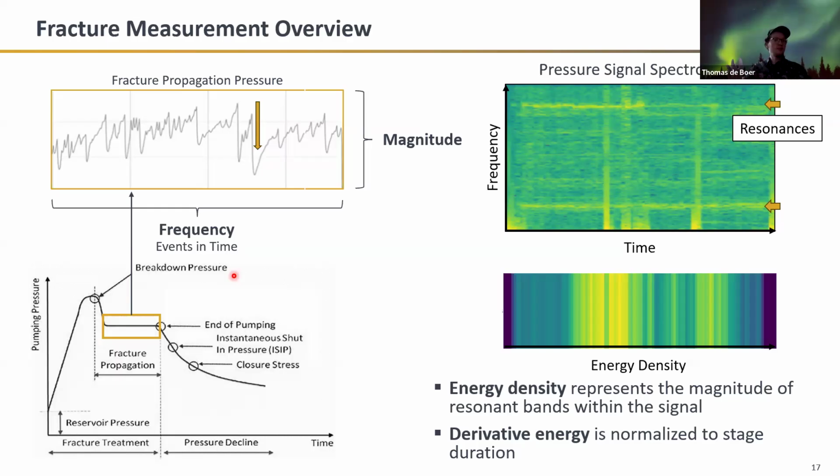Without going into maybe too much detail on the signal analysis side of things, the basic way I would describe this is that a 1 hertz pressure sensor can give you an idea of the strength, but you lose a lot of frequency resolution, obviously. We do also implement, as more of a standard, 50 hertz pressure sensors for this type of analysis. And we have several case studies that are ongoing with clients with up to 1,000 hertz pressure sensors.